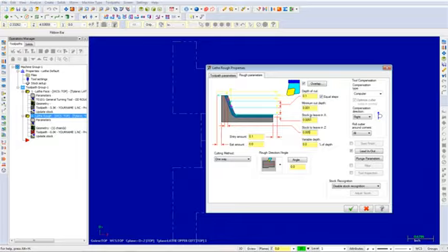Depth of cut sets the amount of material to be removed during each pass. Equal steps sets the depth of cut value to the maximum amount of material that the tool can remove at each pass to ensure equal passes. Minimum cut depth sets the minimum cut that can be taken per pass.